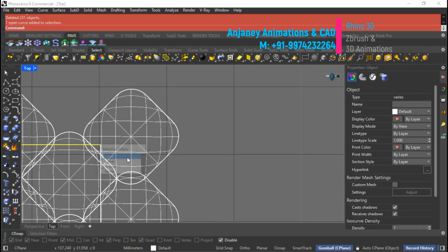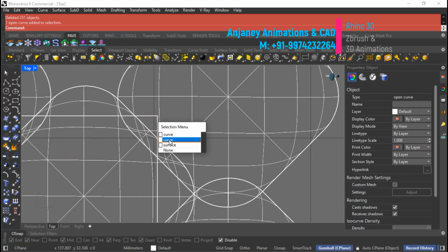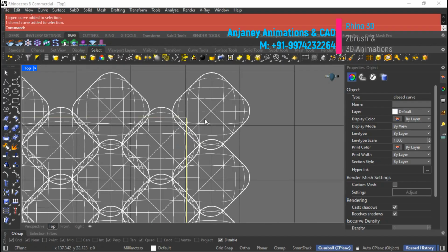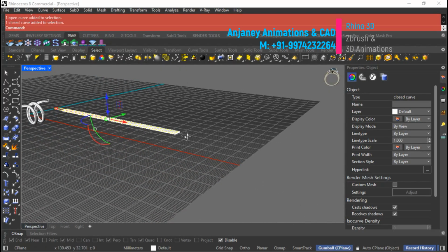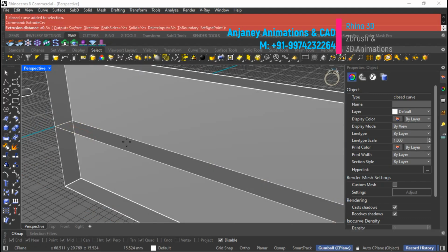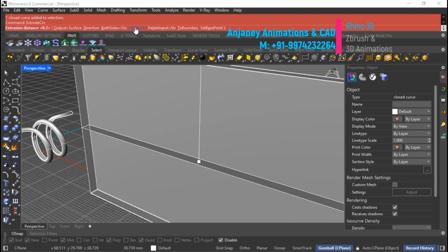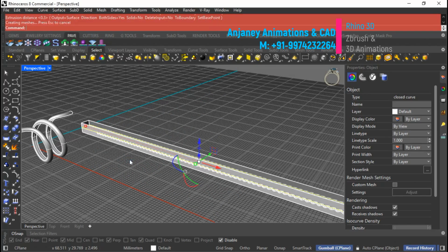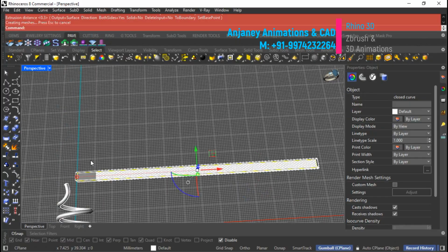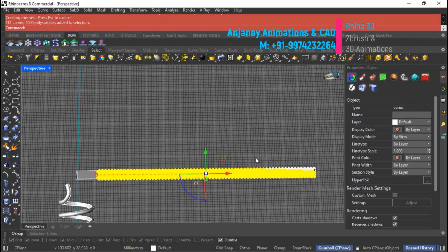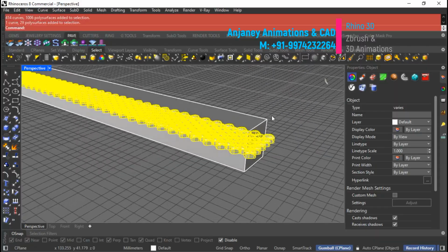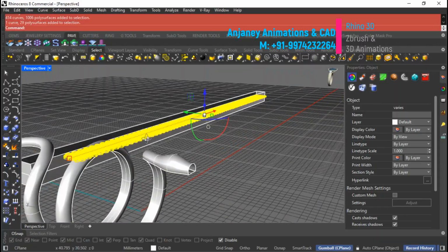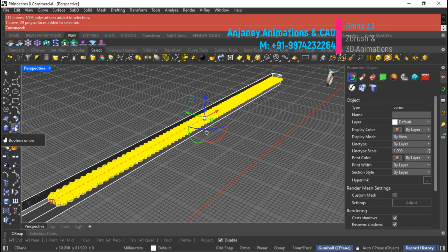Okay, now we also need to trim or cut these objects which are half inside or half outside. We only need the pattern inside of this rectangle which will set the flow. So we are going to extrude this rectangle, and now select all those patterns and use the boolean split command, which will split the extra portions. So go to boolean split.